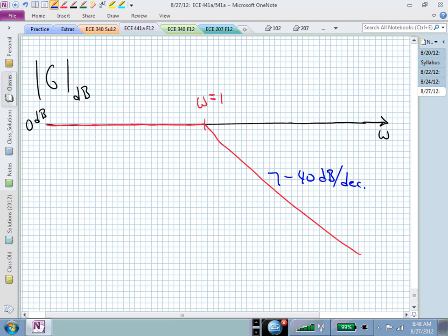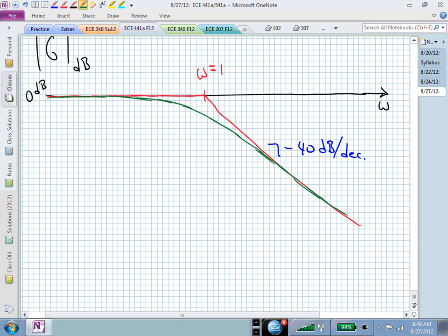If I wanted to look at the exact form, since it's 2 real poles, a MATLAB plot of that would look more like this. It wouldn't have that bump because these are now right on the real axis and there's no ringing. These are critically damped poles. And so now I have that nice smooth behavior in the Bode plot, magnitude response. What's the angle look like?